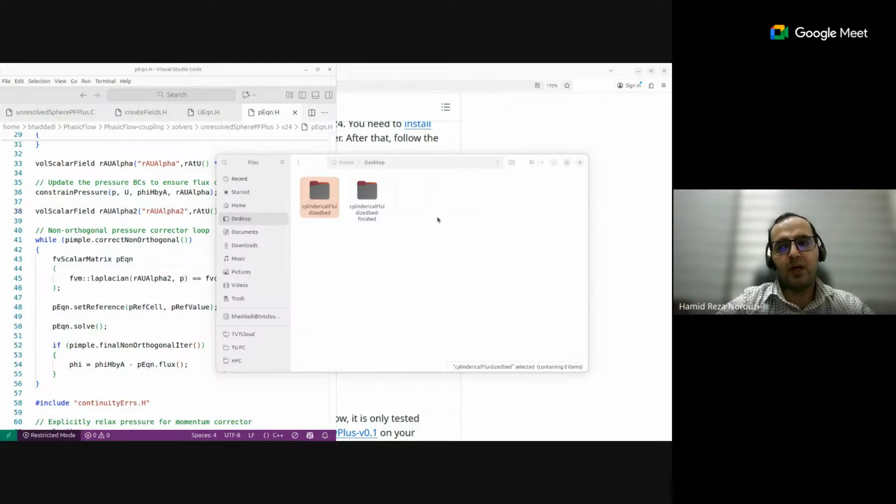If the coupling time scale is lower than the CFD and DEM, we should choose the coupling time scale or coupling delta T. So this is the other important factor we should consider when we are dealing with a system in which the motion of the particles is changing very rapidly. Then we should choose a small enough time step for the simulation to resolve the rapid motion of the particles due to the fluid effects. So this is something that we should consider.